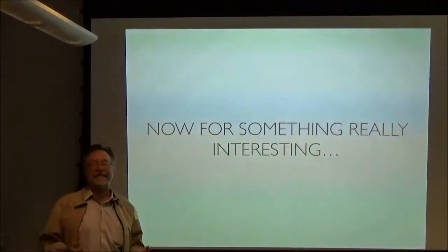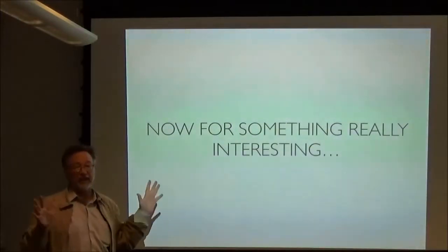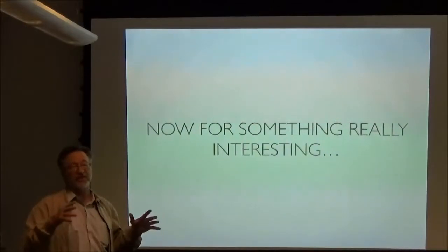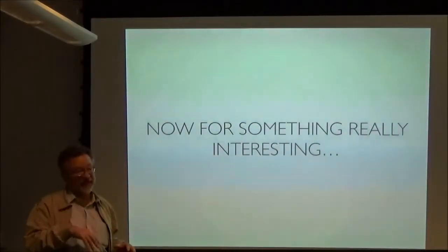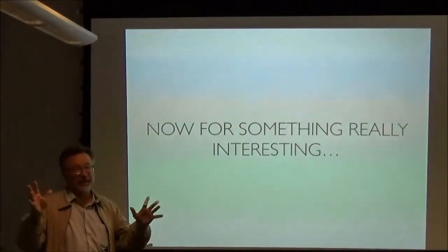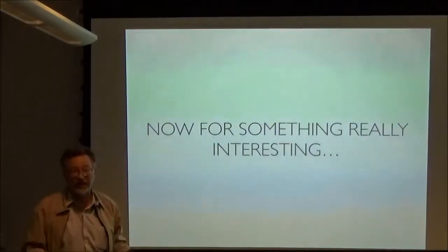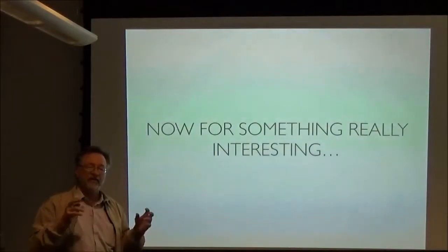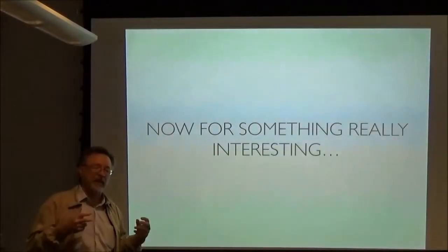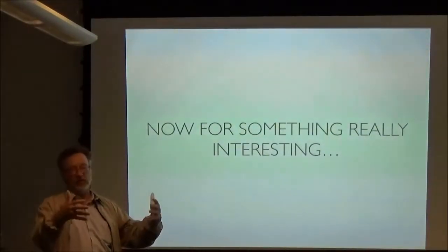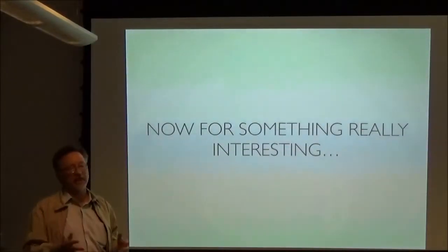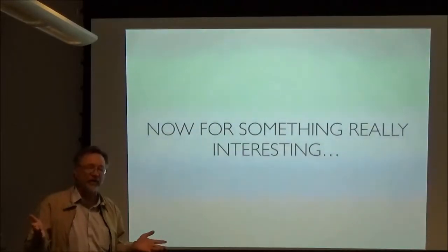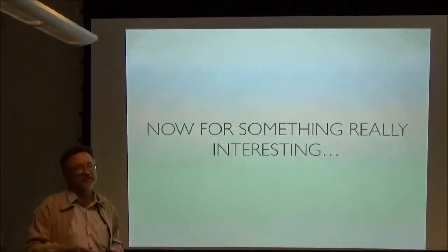The basic synthesis there, I'll just be honest with you, we're going back to 6 bars, so don't misunderstand me. When I say we're just going to get crazy, it's not because I'm going to 10 bars, 20 bars, 30 bars, which is where I would like to be going, but what we're really going to be doing is going back to 6 bars. The one thing I'd like you to understand is our synthesis theory in every situation up to this point has been built on solving 5 quadratic equations. Because that's what the constraint equation is when you apply it 5 times for 5 task positions.